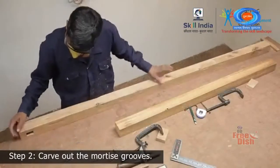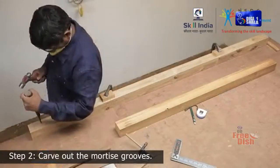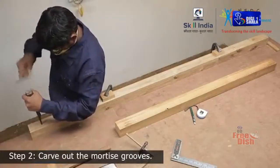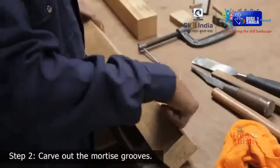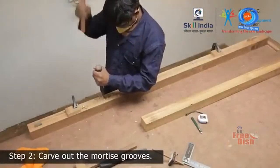Reset the workpiece to the other side. Chop out the waste in the same way till you meet the cutout from the other side. Similarly, chisel out all the mortise grooves on the top and bottom rails.